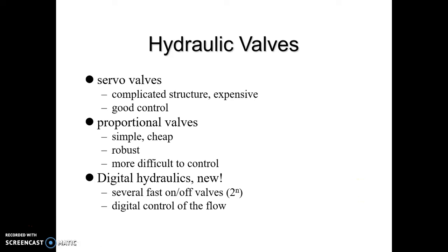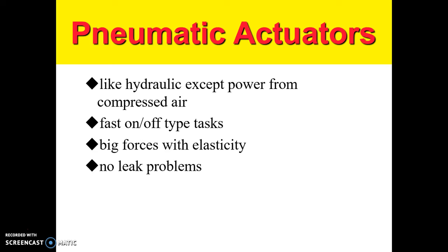Hydraulic actuators work with hydraulic valves. Servo valves: complicated structure, expensive, good control. Proportional valves: simple and cheap, robust, more difficult to control. Digital hydraulics: new, several fast on-off valves and digital control of the flow.